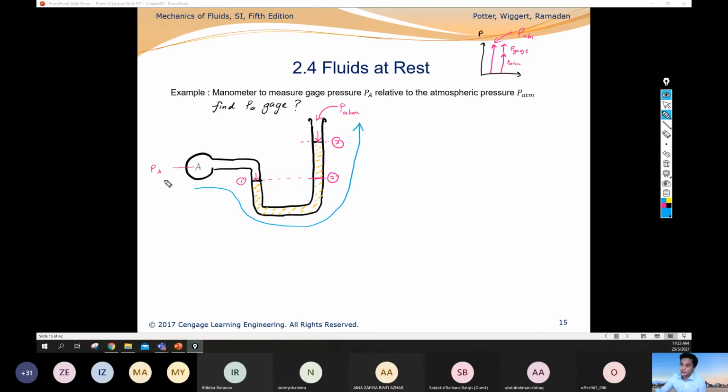All right. So first, we have to write our hydrostatic equation, which is P2 minus P1 equal to negative rho G, Z2 minus Z1. All right. So remember that Z is the elevation. So what do you know about Z, everyone? Is Z a scalar or vector quantity? Z is a scalar. Are you sure, the scalar?